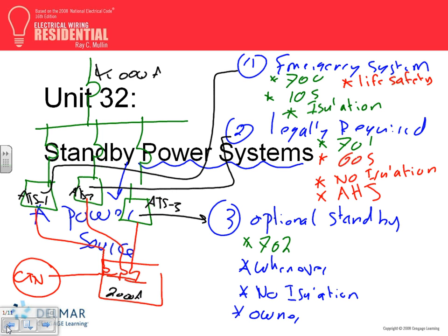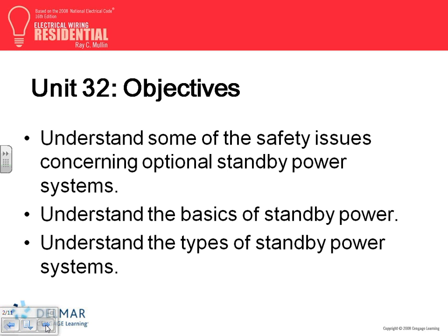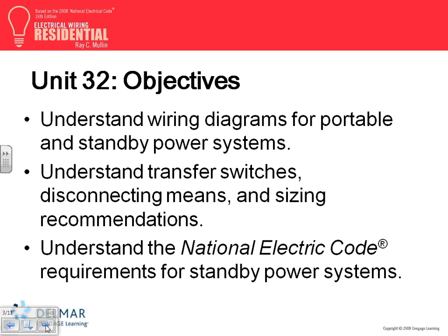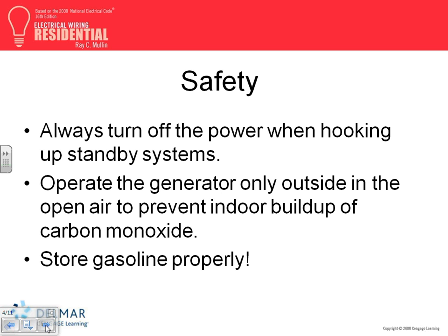So that's basically the ultimate solution that you're going to be doing. I'm going to go, guys, directly into a few things about safety when you have generators. As I said, this chapter is mainly about the power source, not the systems. The systems, we'll talk about them mainly later. If you have a power source, which in reality is going to be a generator, there are a couple of things to do. Always turn off the power when hooking up a standby system.